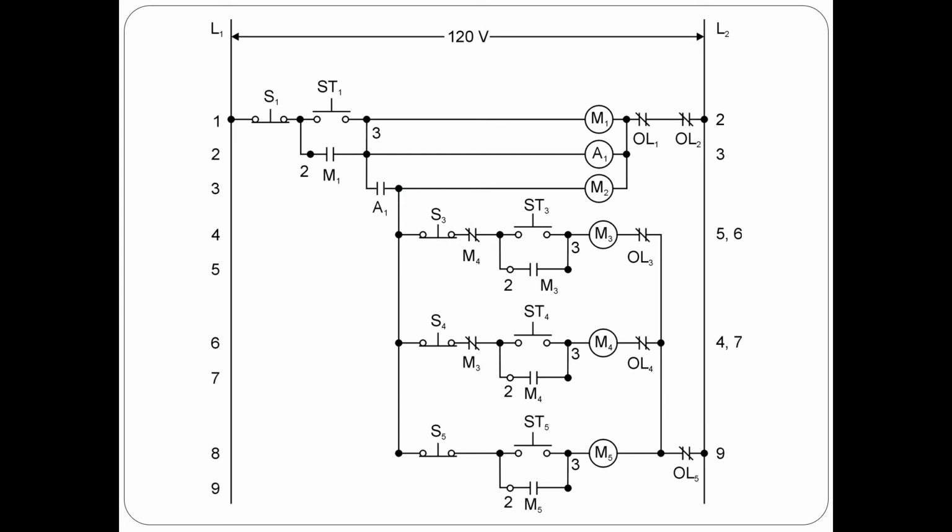Now that we are familiar with some of the things on our drawing, let's take a look at diagnosing the troubleshooting. Here's your first scenario. Coil M5 will start, but as soon as I let go of the button, it stops again and will not continue to run. Pause the video, analyze the circuit, and try to figure out what exactly is wrong with the circuit.